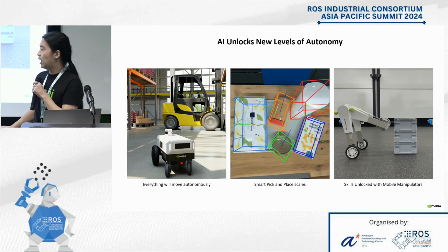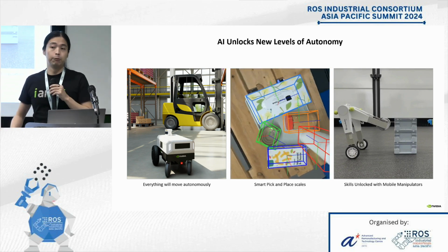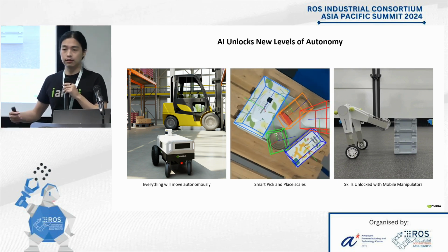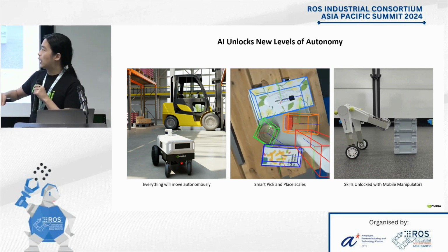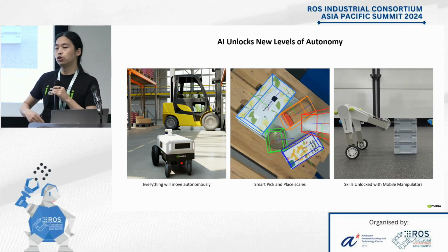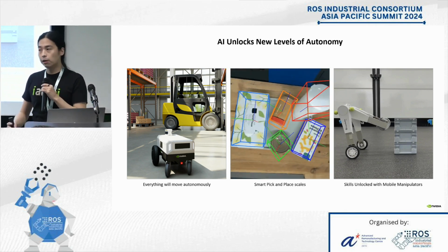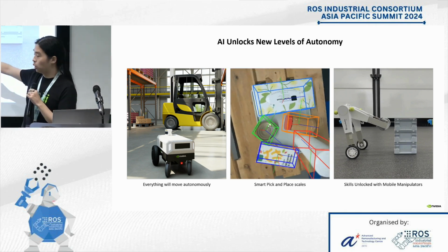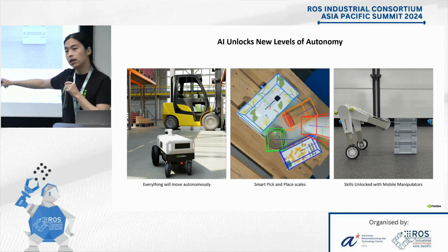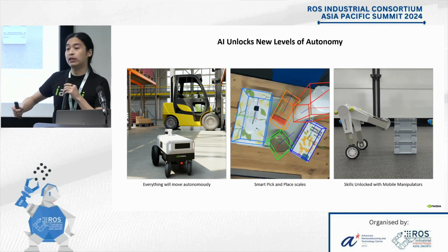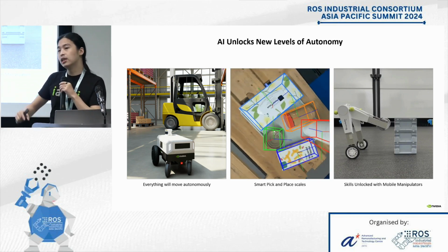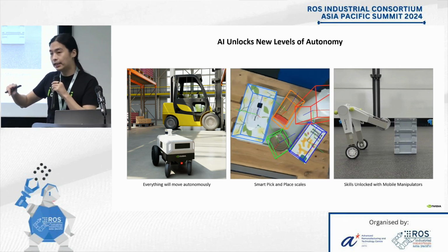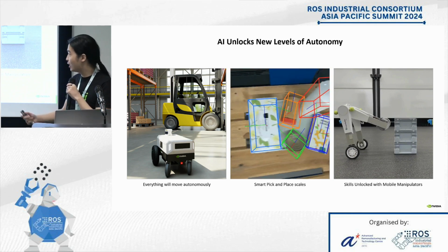So with this AI, of course, you can have more advanced SLAM navigation functions, but it also opens opportunities for grasping, because for grasping, the first step is to detect where your object is and what it is. So it can know where your end effector goes and in what positions, and if it's a delicate object, to use less force in case you crash it.